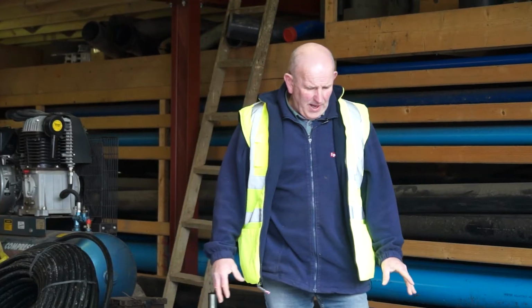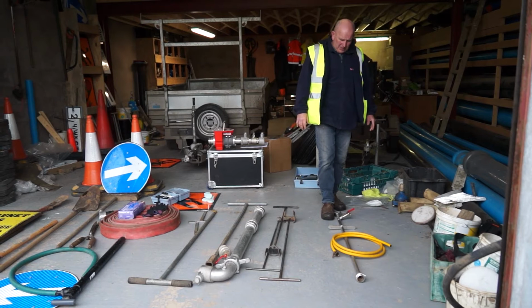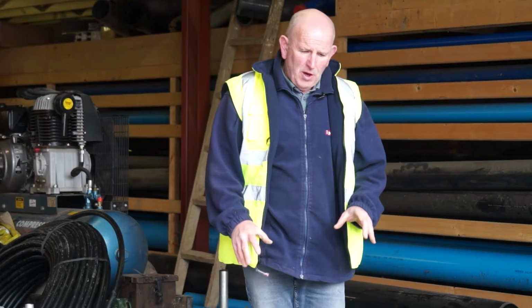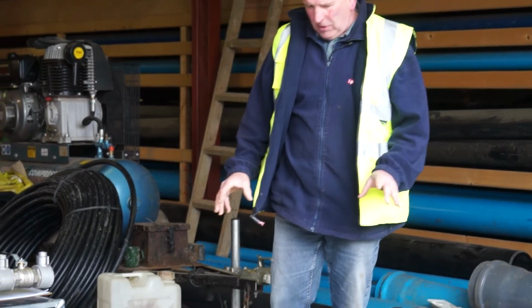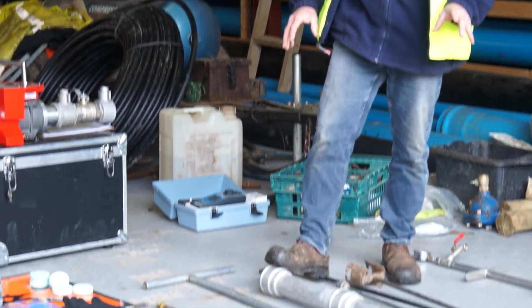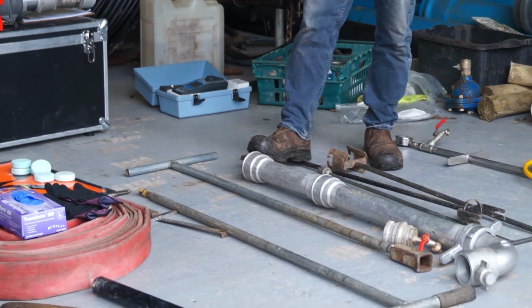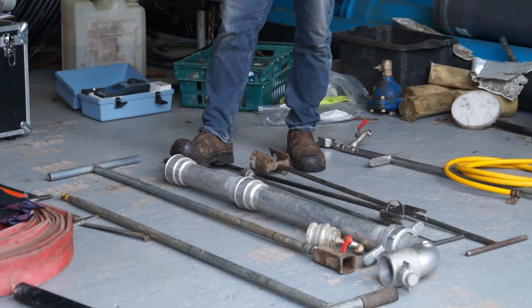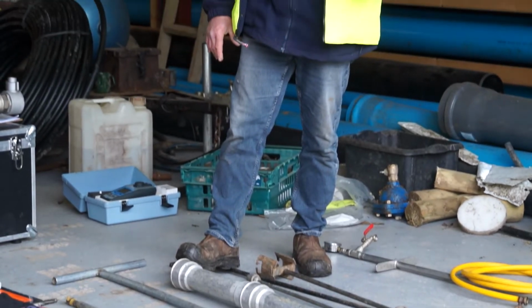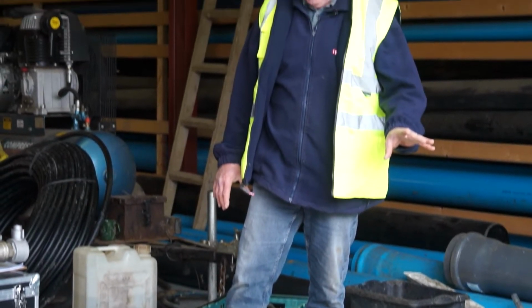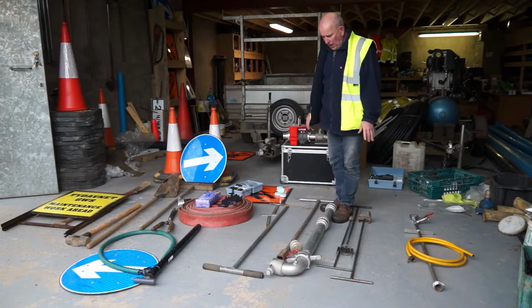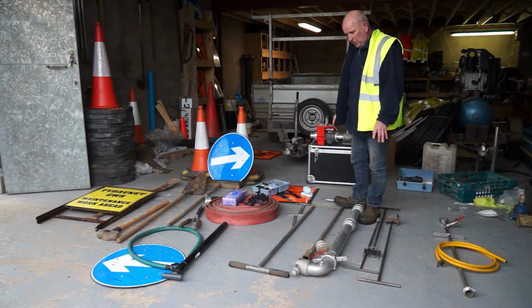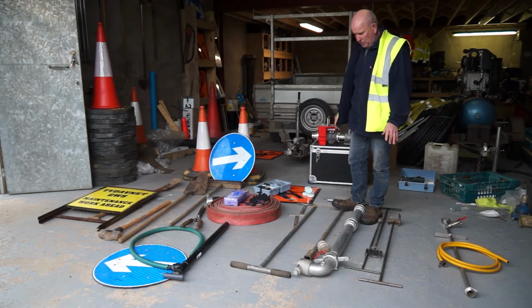I will bring a flow meter and pressure gauge, which we'd use for flushing out at the meter itself. Obviously then when we're doing the main scouring, we can use our fire hydrant, use a standpipe into a fire hydrant, which will be able to, with the aid of a hose, flush out that particular valve. And also a valve key, which is probably the most important thing we have, which we'll use on all the scour valves that we use.